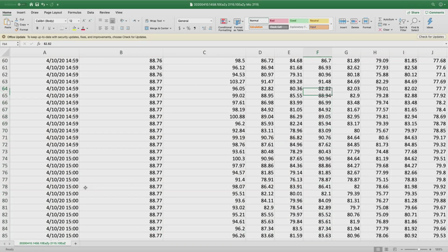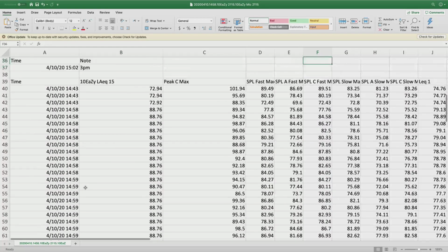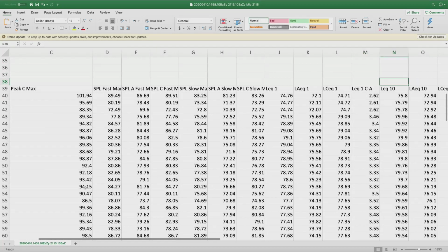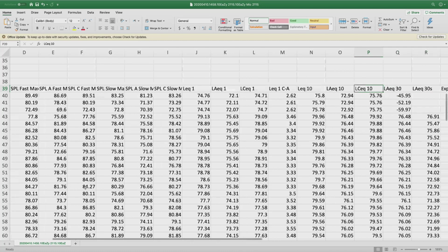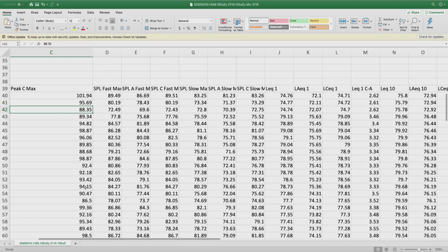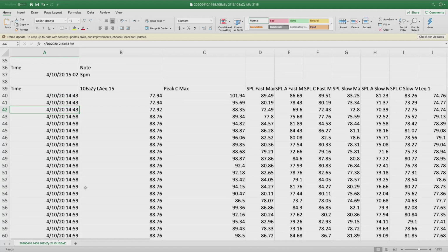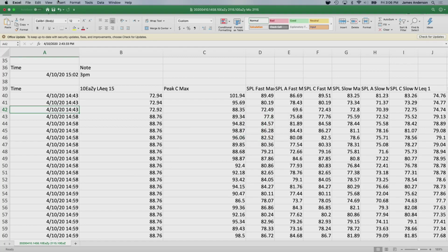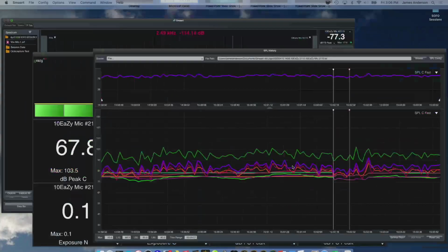And I had mentioned something earlier, the bass ratio, the C minus A, being something that I like to know, and we actually calculate that. So for the LEQ measurements, you'll see there's the bass ratio, C minus A. Or for all intents and purposes, it's a bass ratio for what we're doing because of the nature of a C and A weight measurement. All of these values here, these 3-second values apart, when you look at the history graph of Smaart, that's what's being written to this graph.